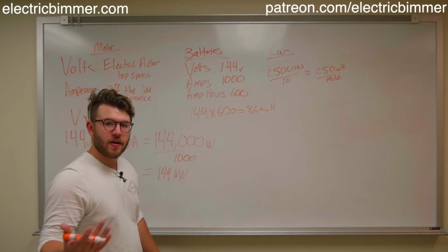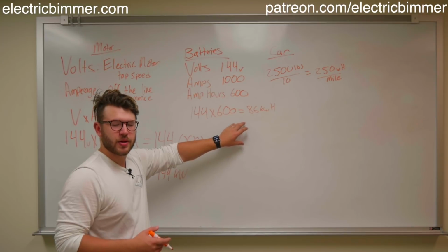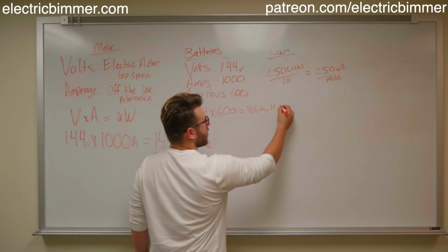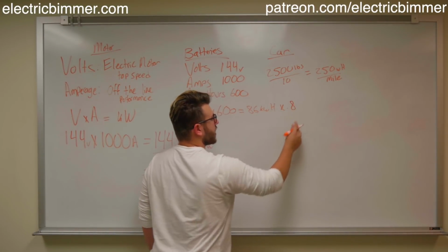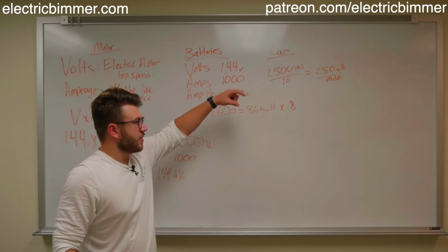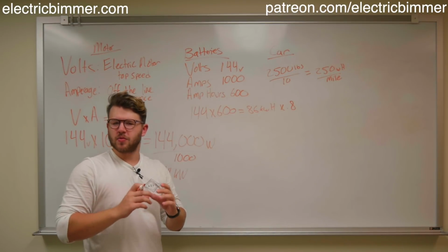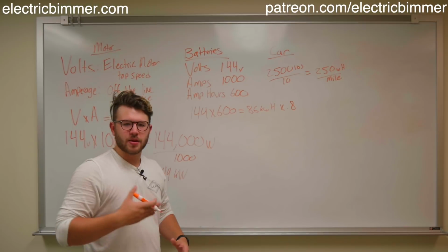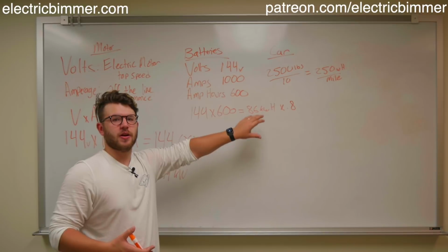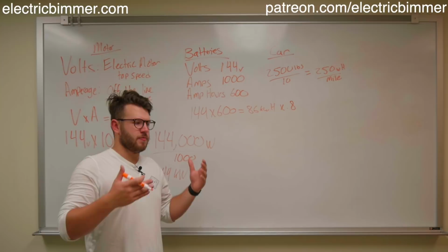So we'll do again the same calculation that we did before, but because we don't have to worry about the lead acid conversion, we don't have to divide this by 2 anymore. But we can go through and multiply it by that 0.8, because that 0.8 again refers to the safe capacity that we can use. We're leaving that extra 0.2 or 20% just as some residual, because if you drain lithium completely, it's going to damage the cells, and they're not going to recharge. This is just playing it safe and ensuring that we are getting the full potential without ruining our very expensive battery.